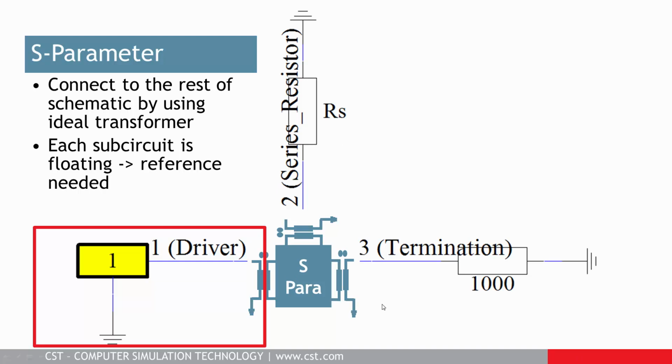So therefore, each of the sub-circuits actually needs a certain reference. And by grounding the one side of the transformer arm internally, so here you don't see this internal ground, but by grounding this internally and then defining a grounding symbol on the actual schematic where we connect our elements, we make sure that the current loop for each of the sub-circuits is closed again.